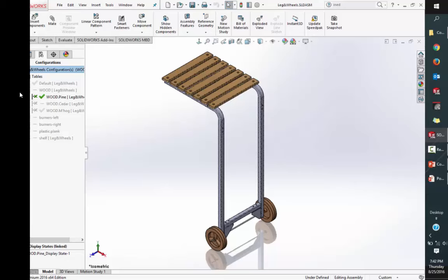One location that we use this in is our sheet metal tool. When you use a sheet metal part, you have the ability to have it formed or flattened. That is a configuration that's made. And if you've ever looked at the file, you'll see it's not another configuration, it's derived. You'll see that it's actually inset under the parent one. The reason being is that, especially with something like this, if there's a change in the formed model, you want that to come through and go into the flat without ever having to worry about it. That's what the derived does for you. So it's kind of a forcing in there.